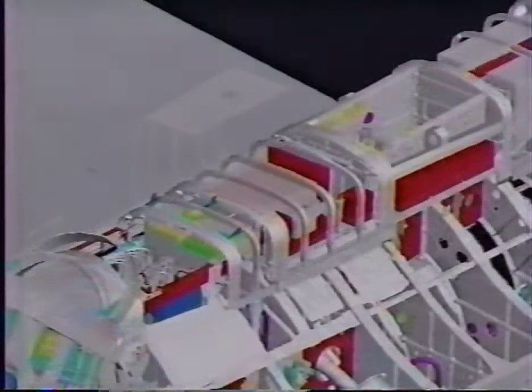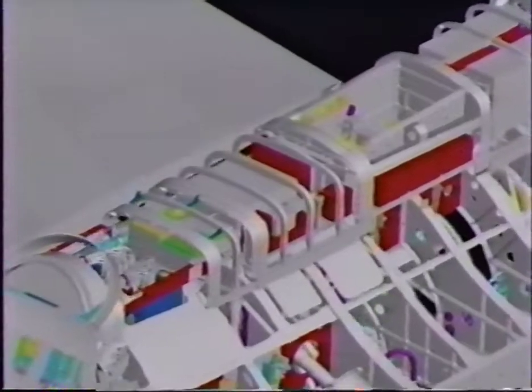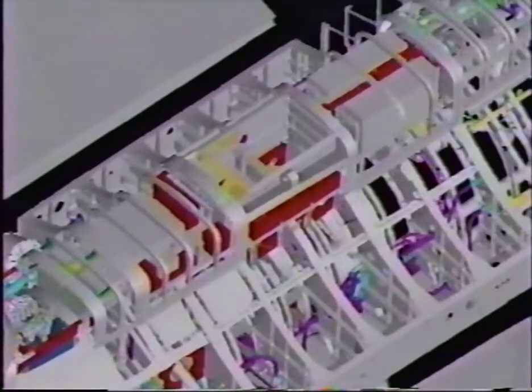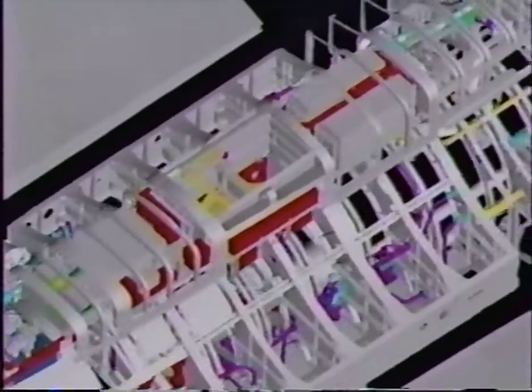The in-flight refueling receptacle has sealed cavities on both sides available for equipment installation. The left-hand side is occupied by 3 data bus interface units used by instrumentation. Dorsal Bay 5 has a one-piece cover providing access to the number 1 Hawk VSS computer and the expansion chassis. Both units are installed on a common shock-mounted support.